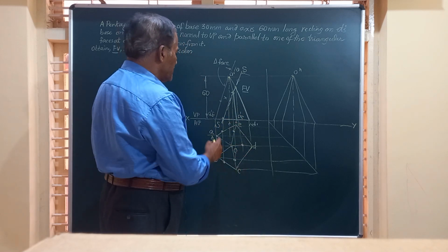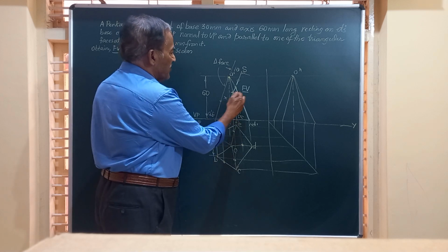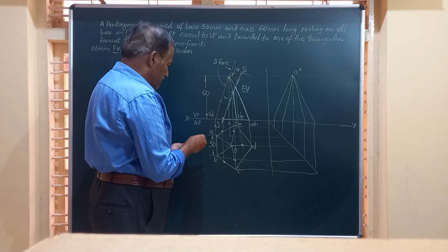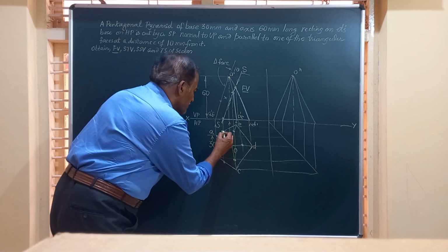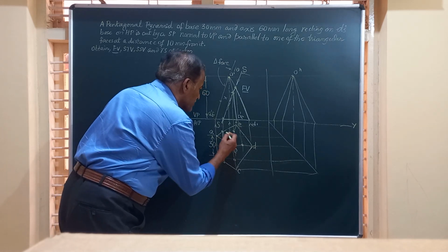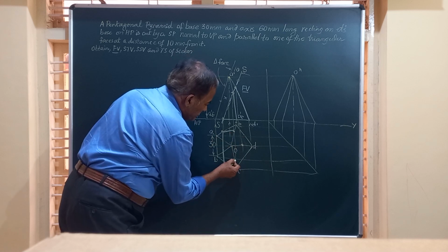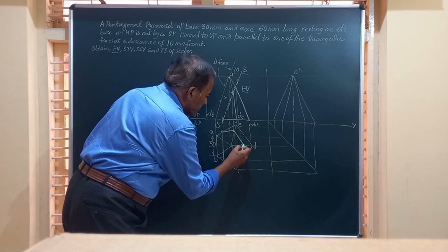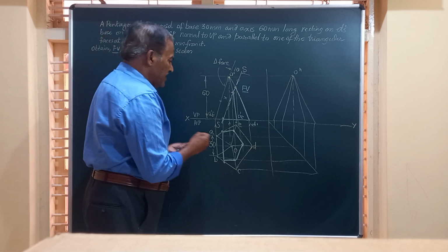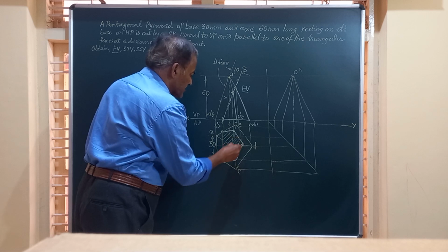Friends, now we have got 2 points for the base, two for the slant edges OC, OE, and one point for this. So totally we have got 5 points here, and the points you have got are to be joined by visible lines. So I am going to join this to this, then here, and finally these points. So this is how the sectional view appears. And let me section this by drawing lines at 45 degrees to the horizontal.